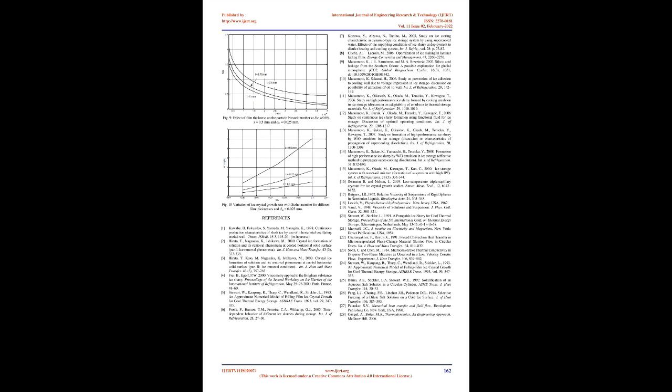The growth rate of ice crystals in the falling film at any y location is the difference between the final and initial crystal diameters divided by the residence time of an ice crystal. The mass of ice growth rate, for a plate of width W and length L can be obtained from the following equation, where the two terms are the length of the control volume in the z and y directions, respectively.